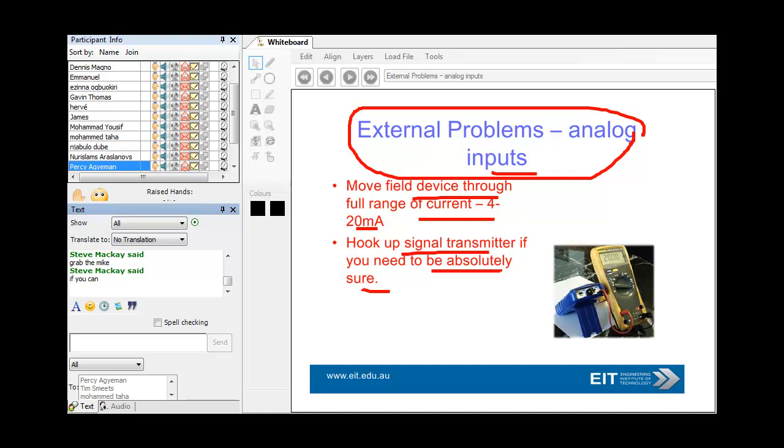Can anyone tell me what was happening with my analog input? Any suggestions? It was extremely painful because it took me a few days to work out what was going on. And in this case, I actually drew on my mainly useless university theoretical background to work out what the problem was. I wasn't reading the analog value correctly. Can anyone tell me why? I'll give you a clue, guys. We also had set up a whole lot of variable speed drives and they were all running.